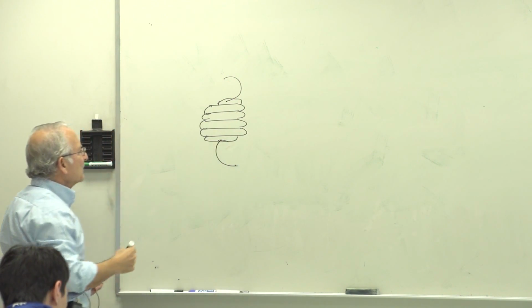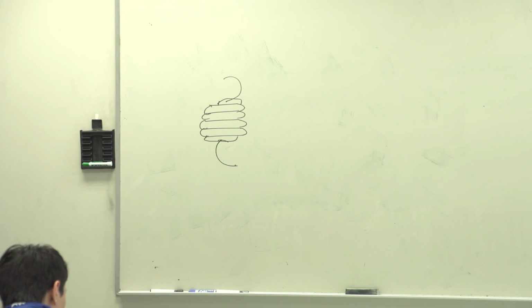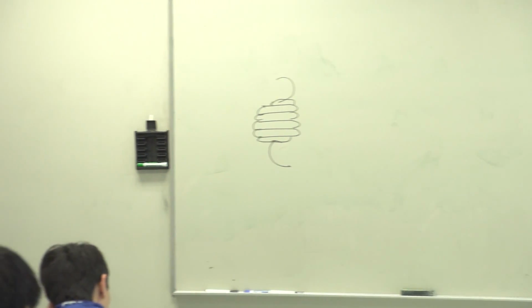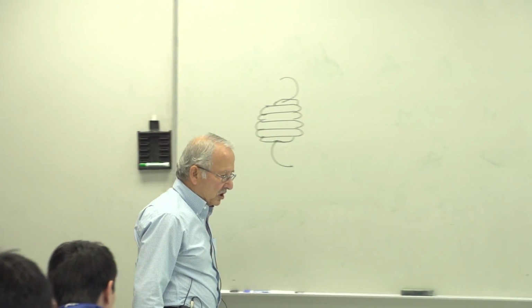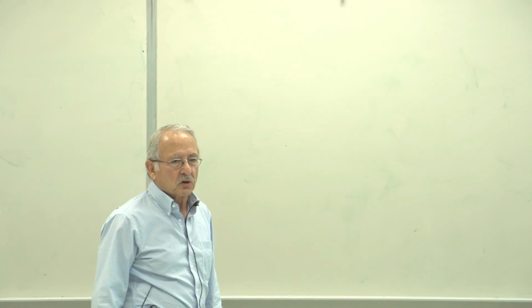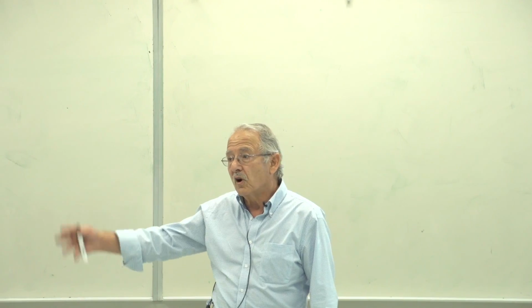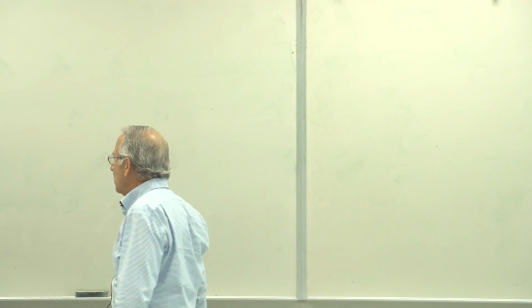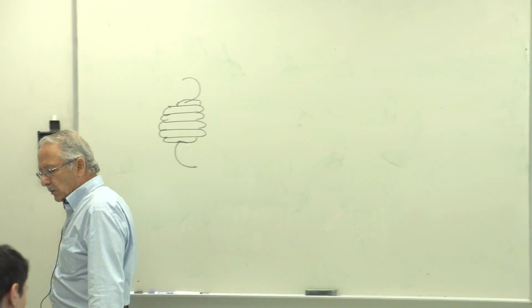We'll take a look at some pictures of those probably next week. So that's called a tension spring. And it's wound shut with a preload so that initially when you apply a very small amount of load, you basically get no deflection until you overcome that preload. But again, we'll take a look at that in detail a little bit later.